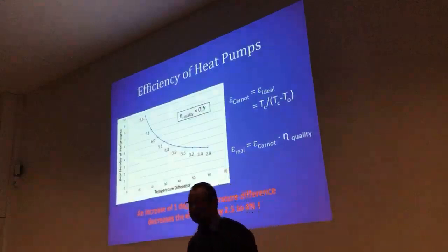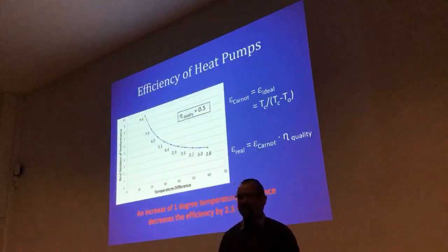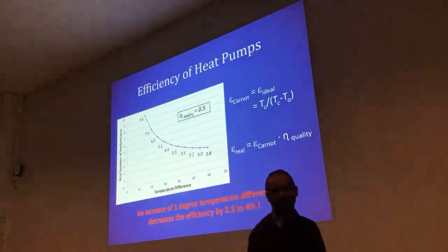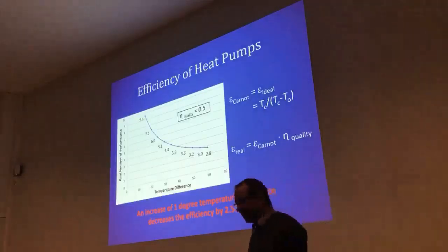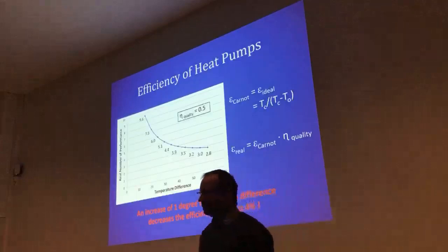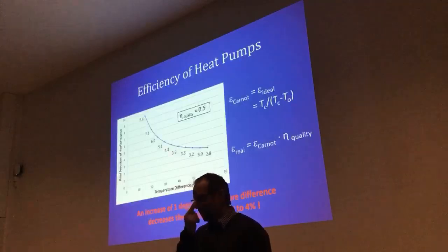In general, heat pumps have a good reputation for being very energy efficient, but the daily practice quite often looks very different. The main reason is that the temperature difference between evaporation at the heat source and condensation at the heat sink is much higher than proposed.